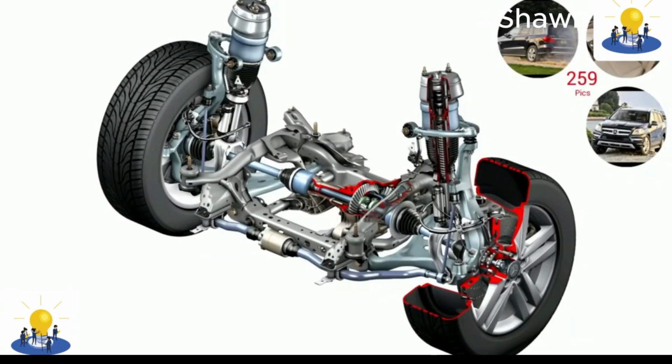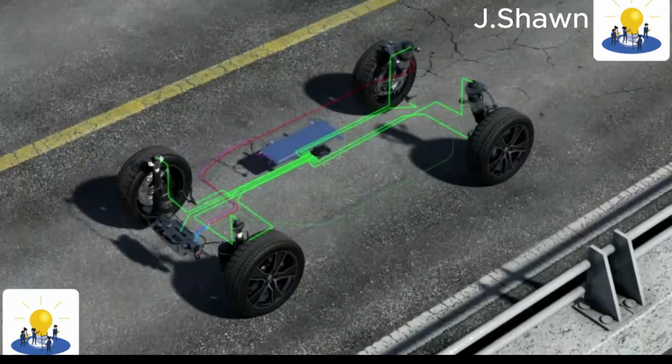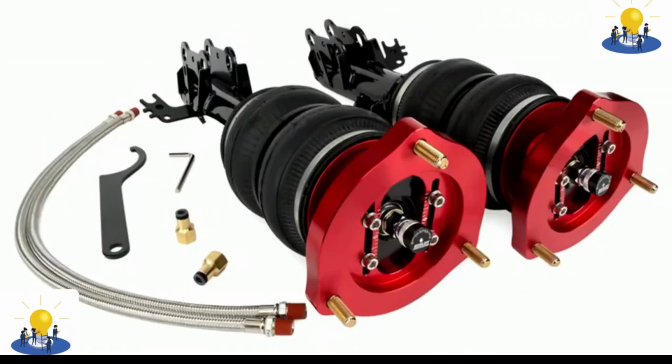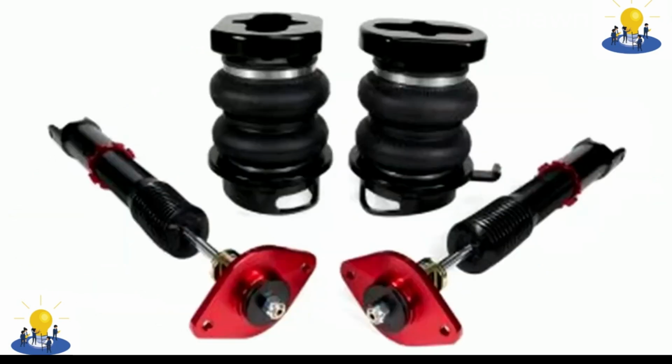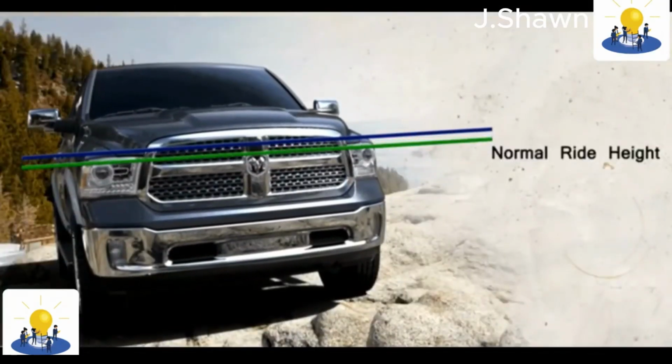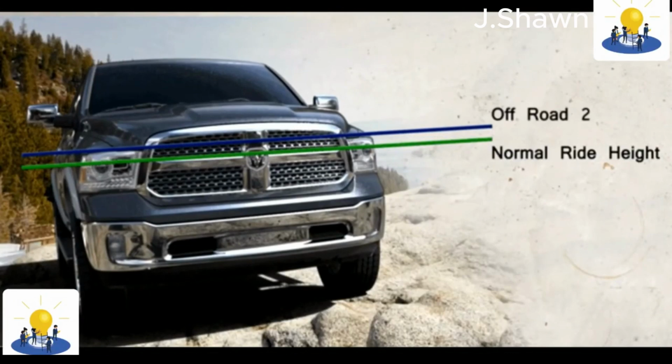The Mark VIII suspension settings were also linked to the memory seat system, meaning that the car would automatically adjust the suspension to individual drivers. The control system in the Mark VIII can lower the suspension by about 25 millimeters, or 1 inch, at speeds exceeding about 100 kilometers per hour, or 60 miles per hour, for improved aerodynamic performance.